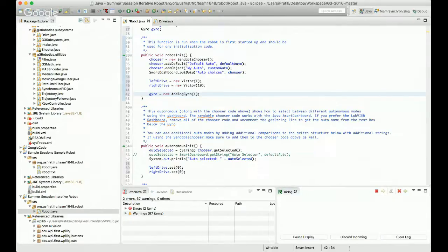And that's a concept that you should always keep in mind. Any signal that you're reading from, or any value that you're receiving from a sensor, is ultimately just a number in terms of code. So you're going to have to give that number meaning, whether that's a number corresponding to the heading of the robot, and that a change of 10 in that physical signal is a change of 10 degrees in the robot, or that's an encoder where 10 ticks is 10 inches or 10 feet or 10 millimeters. You just have to give context to all of these signals.